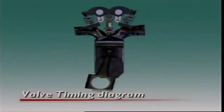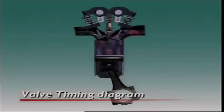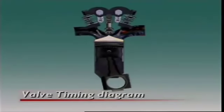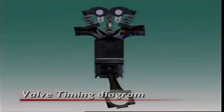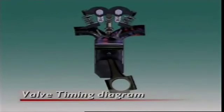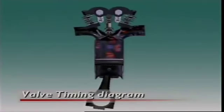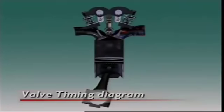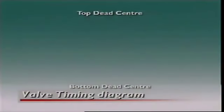In practice, the intake valve usually opens earlier than top dead center and stays open a little past bottom dead center. The exhaust valve opens a little before bottom dead center and stays open a little past top dead center. When the valves actually open and close can be measured by angles. To make these angles easier to read, let's use a spiral instead of a circle.